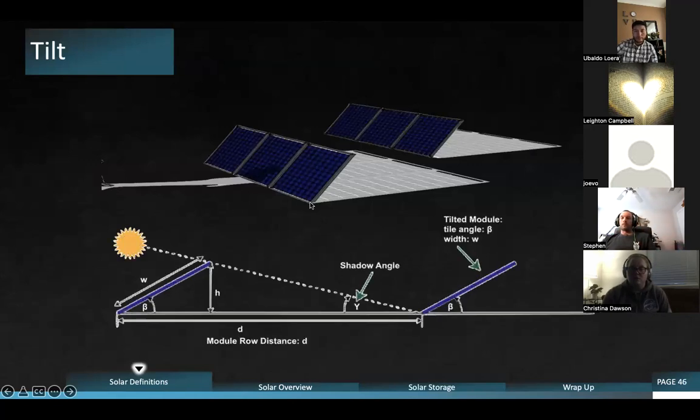So here's an example of the actual shading, so you guys can take a look. These are factors that are being done by the project managers. We want to make sure that they're spaced perfectly apart so that when the sun hits it and it casts that shadow, it comes up towards the panel, but it doesn't come onto the panel. Like this guy is shading this part of the panel and he has partial shading. Okay, this is what we're looking to achieve when we do an open mount system on a flat roof.